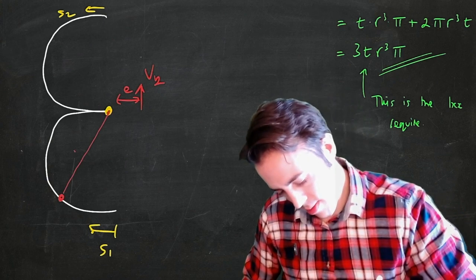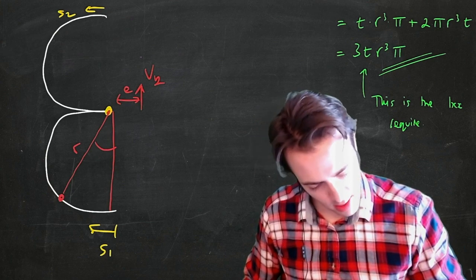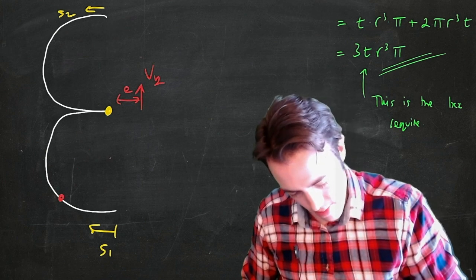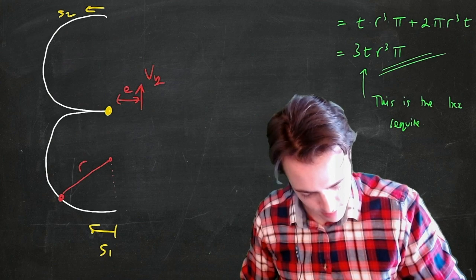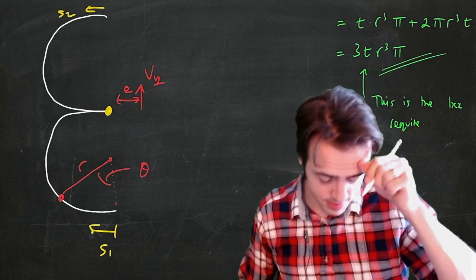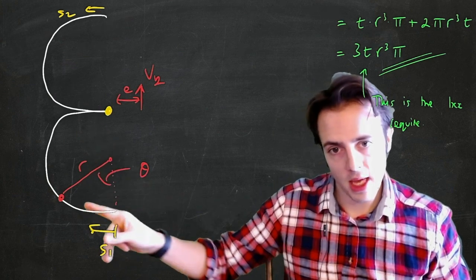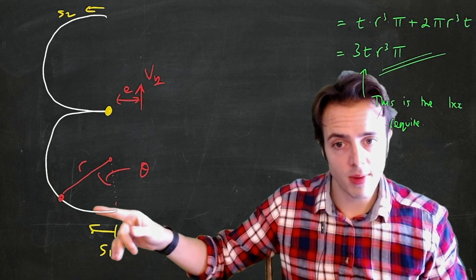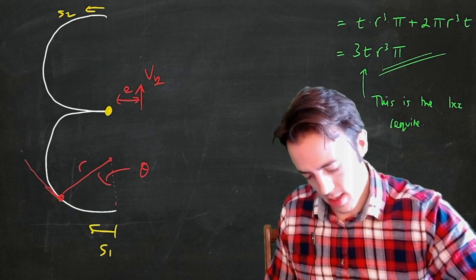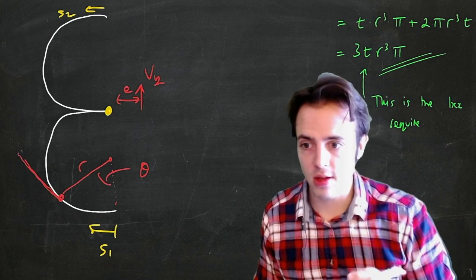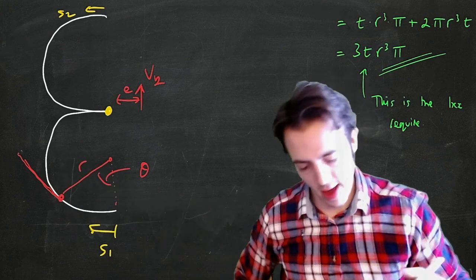So let's draw this. This is my radius R. Sorry, that's not what I'm doing. That's the wrong shape. This is where I happen to be. That is R. This here is my theta. Because this is a curved shape, the force that's being applied because of that shear flow is going to be equal to the tangent to this wherever we happen to be. So where I am here, let's pretend I drew a perfect tangent. That would then be the component, the actual force in this direction.